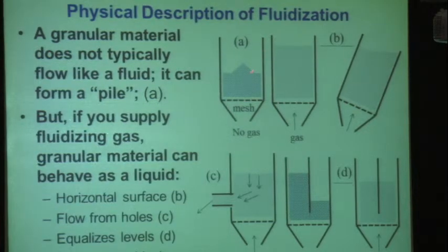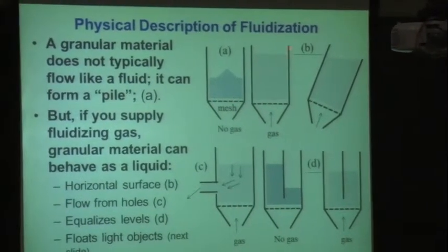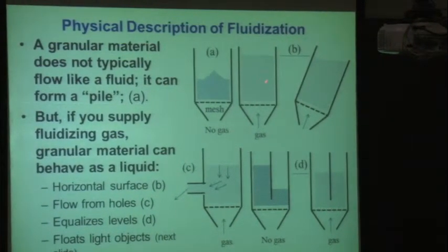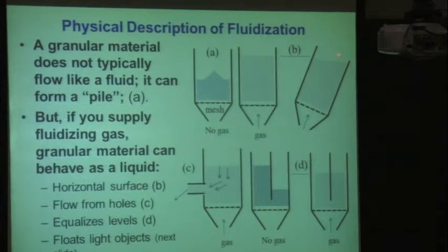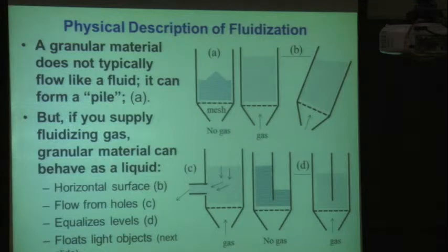All right, that's what I'm showing right here. Now if you add air or a gas to the bottom of that, you'll start to fluidize it, and the volume will grow a little bit and it will look just like a fluid. If you tip the vessel over, as I'm showing here, it will level that surface just like a bottle of water. Where's my bottle of water that's not full, right? That's what a fluid does. I tip it at an angle and it takes a level surface. Well, solids will do that too, as long as you put that fluidizing gas in there.